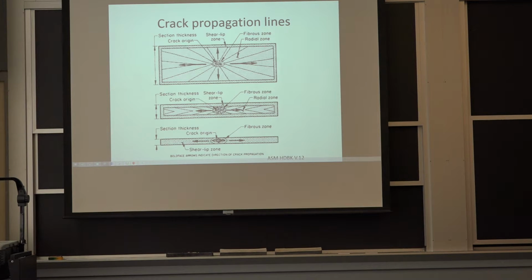Good question. So you have to know the load applied and the capacity. If you have cyclic loads, there are materials that are more resistant to that crack initiation, and that's what you're looking for. The other thing that you can look for, in the context of landing gears, for example, is you just assume there'll be a crack to begin with, and you don't want that crack to grow big enough to cause a problem.